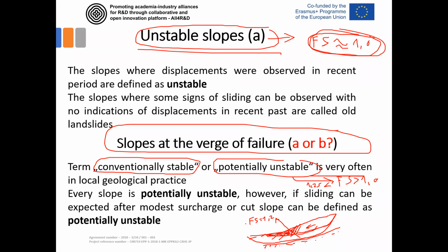So any construction we perform can bring it to unstable areas. That's why in this condition we have to define some supporting measures, some retaining walls, some anchor walls, and so on to support this excavation area and to increase the stability of this surface above the excavation.